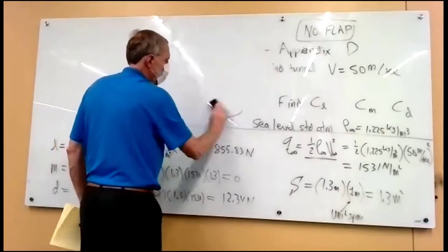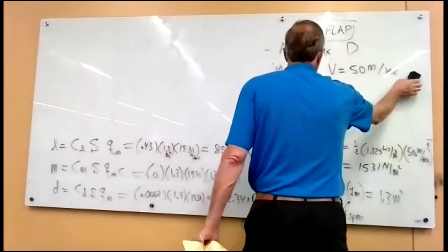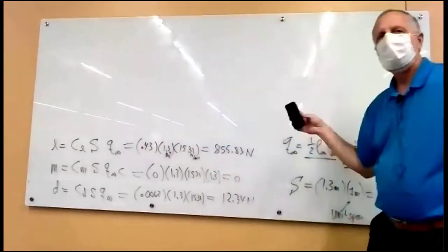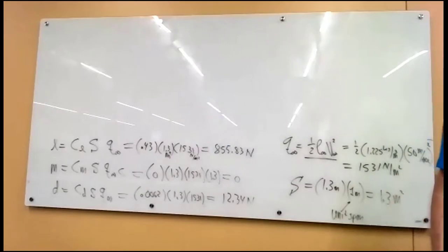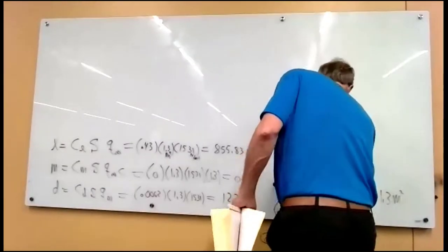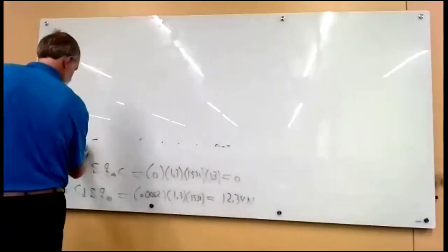If it's almost infinitely long, the airfoil data is going to be pretty good. Whereas if it's a real short, stubby wing, then you get a lot of flow around the wingtips, and that flow covers most of the wing because the wing's real short. So the parameter that measures how long and thin a wing is something called the aspect ratio.